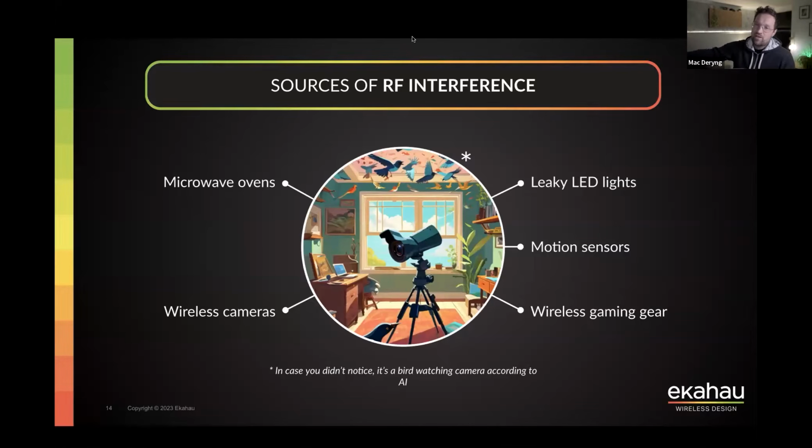Motion sensors. When you have those little motion sensors in the corners of the rooms, you move next to it, and then you will see in the historic spectrum view when you're doing a survey with Ekahau, iPhones, Pixels, and the Sidekick, whatever you use, a slight, tiny, narrow interference that can completely kill your transmission on this particular affected channel, very, very frequently on 5 gigahertz as well.